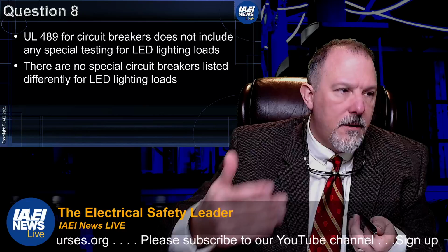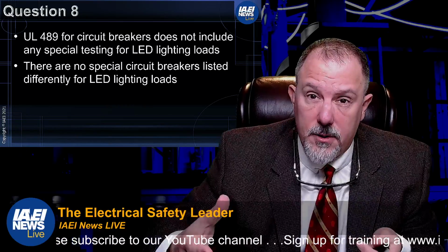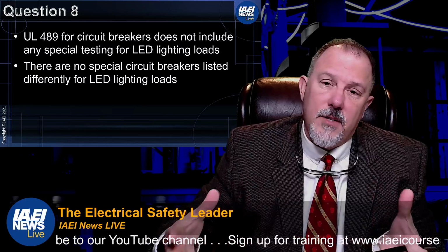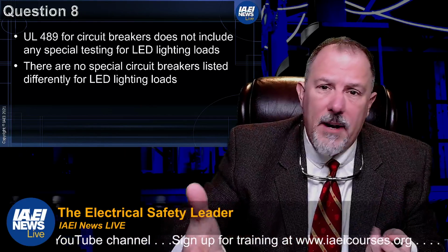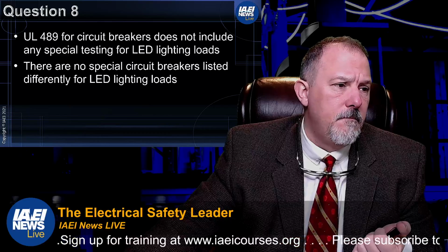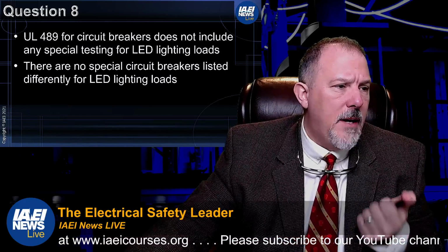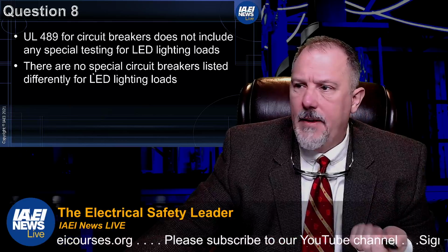You want to know the inrush current on the driver, because that's where the AC to DC conversion occurs, and it's an inductive circuit. That's why we have poor power factor associated with these solutions. All right, so that's my discussion on that one.